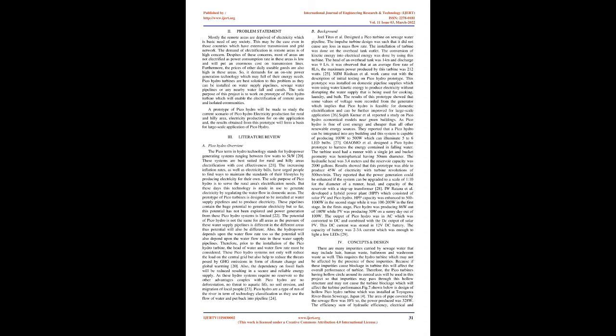Propeller turbines. The reaction turbines which are in operation so far are mostly propeller type, owing to their simple design, efficiency, and cost effectiveness. Figure 1.6 shows the design of the propeller turbine having 6 blades on its runner. The striking rate of water on these blades is constant irrespective of their blade pitch, which is either fixed or made adjustable.